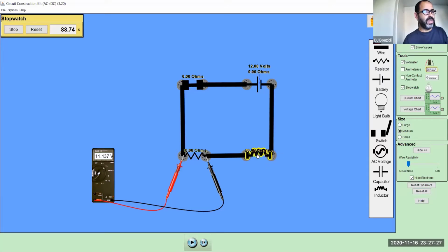And this one, change the value of it. You can just right click and change the inductance to the value that is needed, 10, which is the lowest value in this case, okay? And leave the resistance at 10. But the capacitor, when you add it, make sure to change the value to the lowest value possible, which is 0.05 farads, okay? So now, you're going to build this circuit, basically.